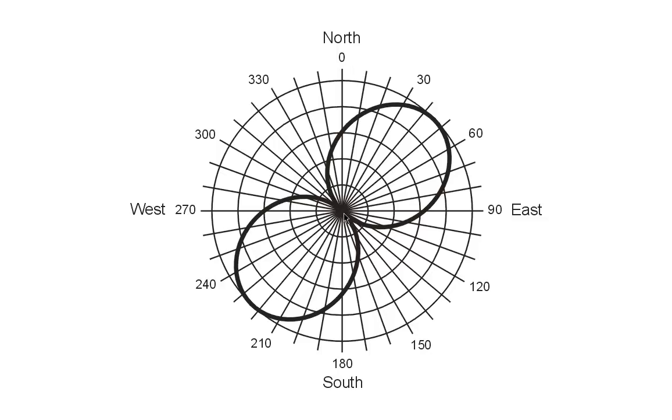The station, or the antenna itself, is located right here in the center, and we're looking straight down on the situation from far, far above. These ellipses or curves represent the relative radiation intensity that we would expect to see in various directions. So, for example, going straight northeast, we would expect to see maximum radiation from this antenna. The same thing would be true going straight southwest.